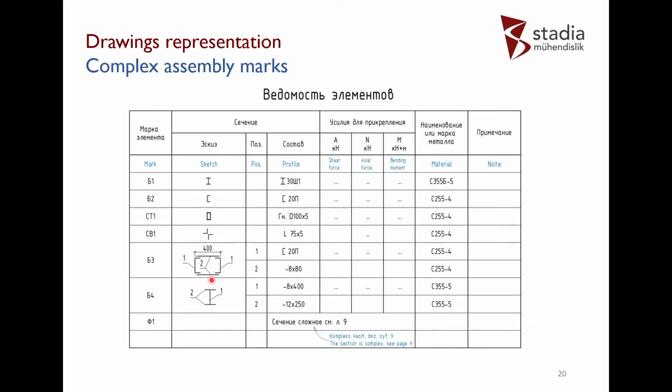Another example is a welded I-beam. Also, this is the position of the element, so it's easy to understand what kind of section it is. And support forces. It's very important to understand that these are not the maximum forces in our element. It's not the moment in the middle of a pin-connected beam, because that's totally not correct. It's support.